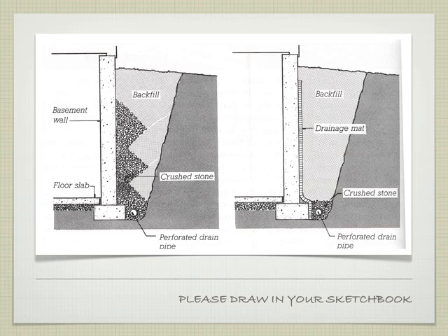I've seen it done where they put the drainage rock in anyway. The truth is that depending on what soil you have, where's that sample passing around? Did it stick back in the drawer? Do you mind? So, depending on what soil you have, if you have too fine a soil, you're going to clog this, and it's not really going to serve its purpose.